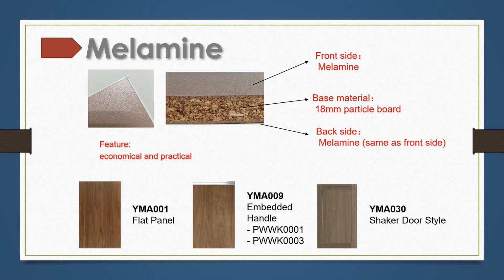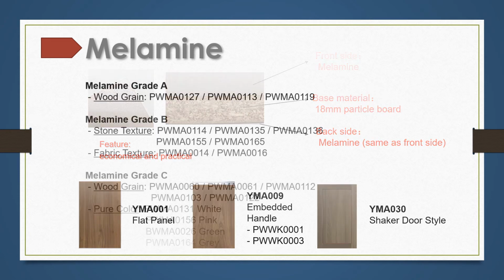For paints, we mean we directly do paints on the base materials, dry it, and polish it. Lacquer and solid woods are processed this way. By the way, solid wood is a special option that is more of a natural panel than an artificial panel. It has a special production process, including drying, antiseptic treatments, killing all bugs inside, removing sugars and fats, and a couple of other treatments. And that's why we don't list it in the three base materials categories of artificial panel.